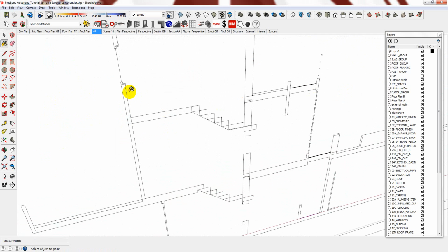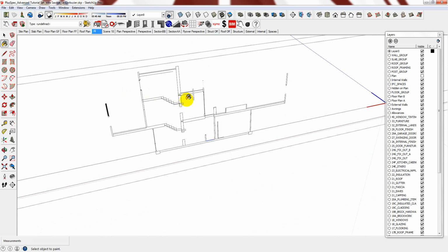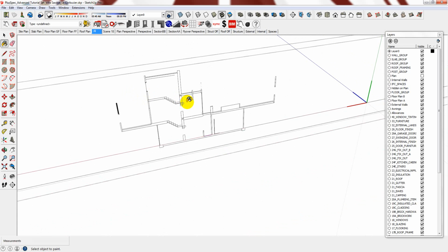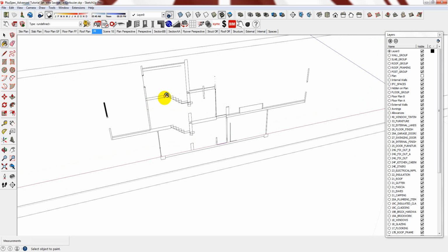However, if this is for a detailed section, you can add any necessary lines, paint hatches, and so forth. Just take the time to tidy it up. Once you've done it a few times, you'll be surprised at how quick this actually is. If a section is at a scale of 1:100, I actually prefer to simply assign a color, as I am from the school of thought that a 1:100 section is more about the form and the space. However, do whatever suits your workflow.